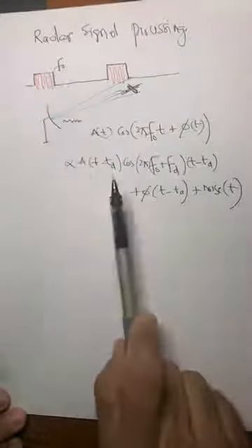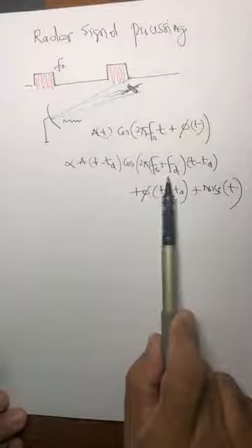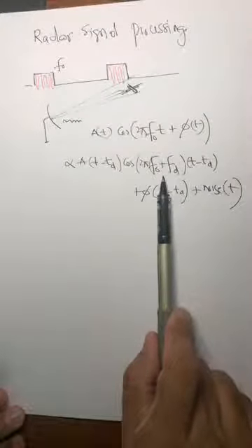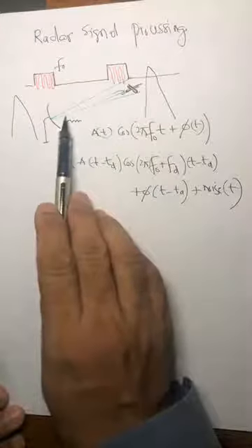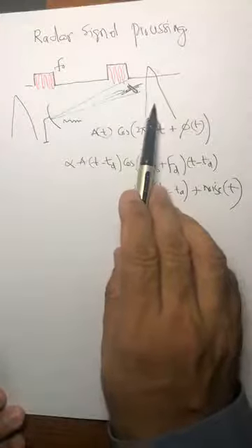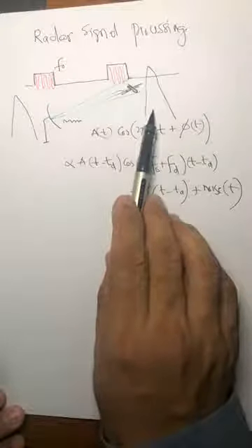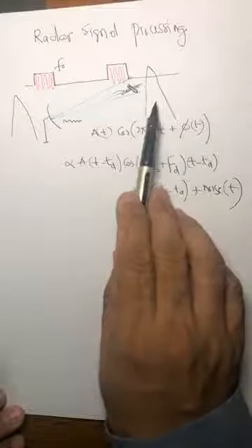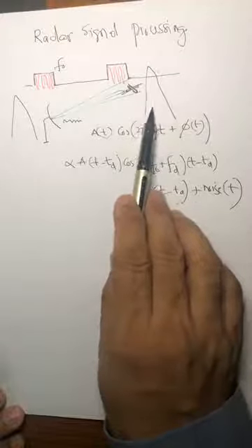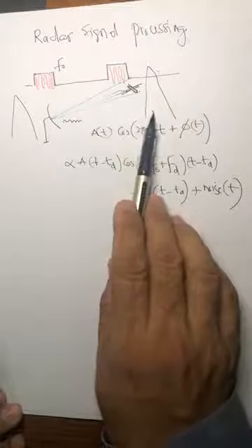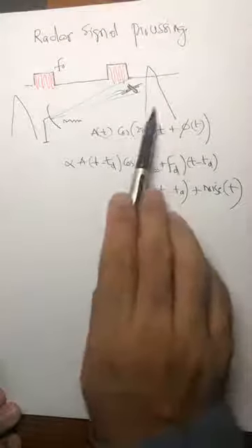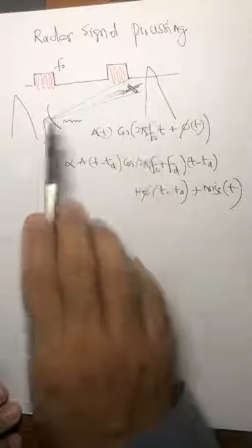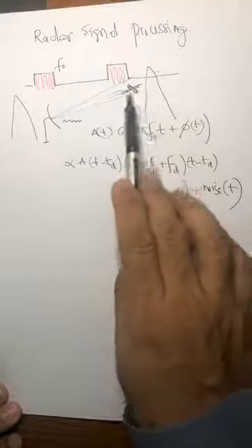So DFT is also very powerful in finding this cosine, because there may be hills somewhere. Once this radar signal strikes a structure like buildings and hills, there will be no Doppler shift. So this is clutter. You will easily be able to figure out, once you take the FFT, that if you have a high return from a hill which does not have any Doppler, it means it is coming from a static target. On the other hand, if it is coming from an aircraft which is flying towards you or away from you,